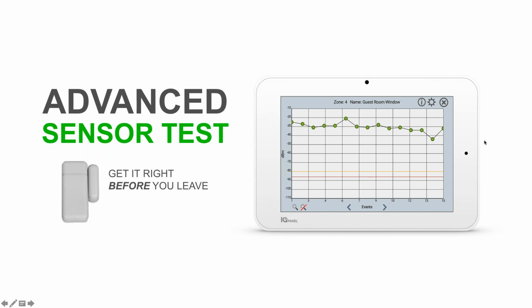And like I said, if your techs are checking this before they leave the house, they should never go back for a sensor losing supervision, because this will tell you if it's talking strong enough or not. This will tell you if you need to add a repeater or not, right?